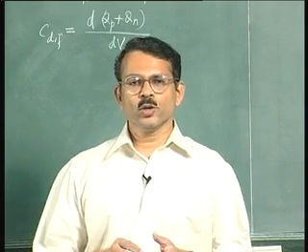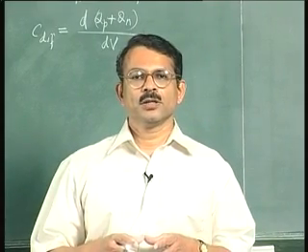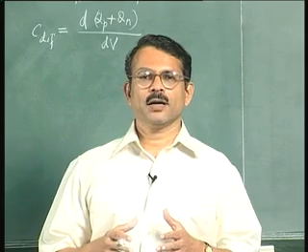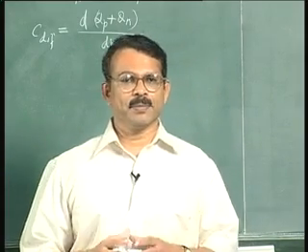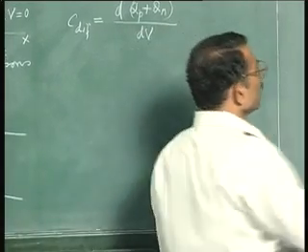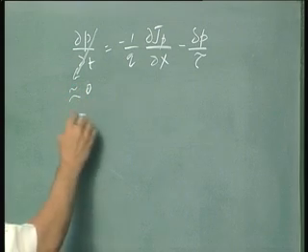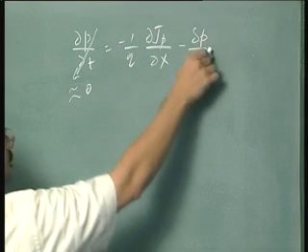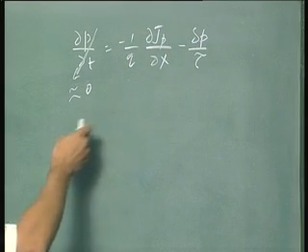Now you are going to use this exponential distribution obtained under steady state conditions to estimate the changes in the charges also under non-steady state or time varying conditions, the voltage varying with time conditions. Which means that you are setting this dp/dt not exactly equal to 0 but approximately equal to 0, so that you can still use the continuity equation setting these terms equal to 0 and get the exponential distribution and then work with that.